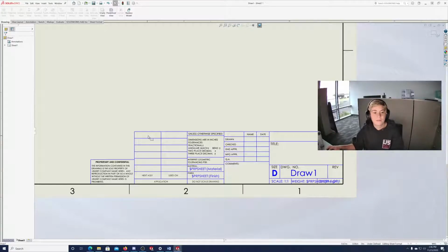They'll say, this is Rev A, and they'll put right here what we changed. This measurement was 1.5 inches, now it's 1.75. And if there's another revision, that's going to be Rev B, and they'll describe what changed over here. And Rev C, and they'll describe what changed over here. So that's what would go in that area.